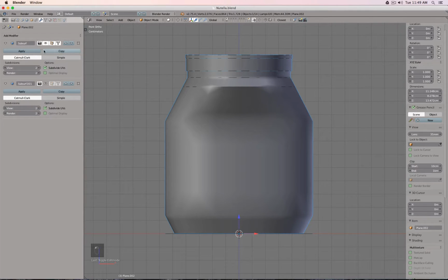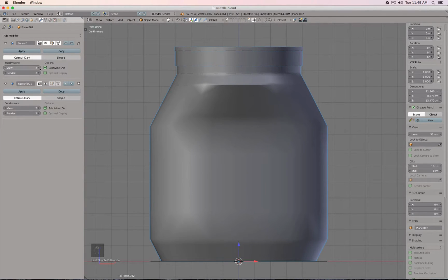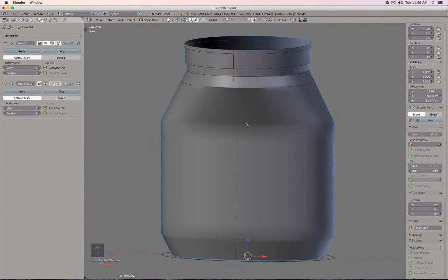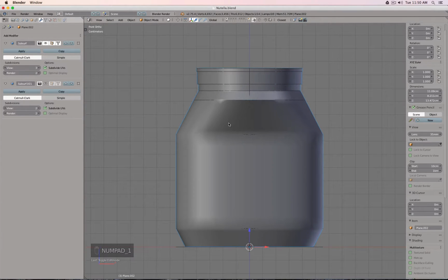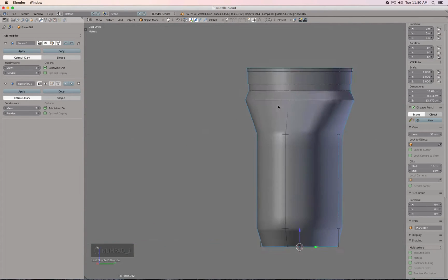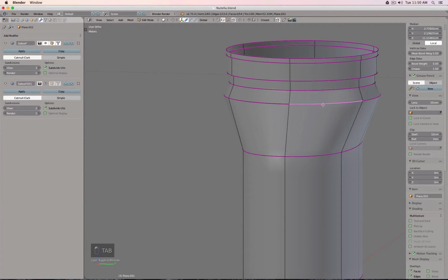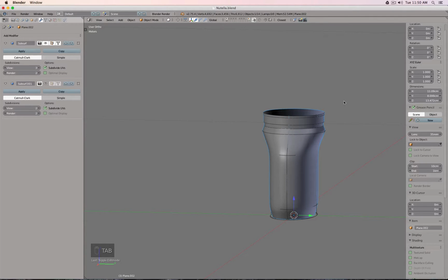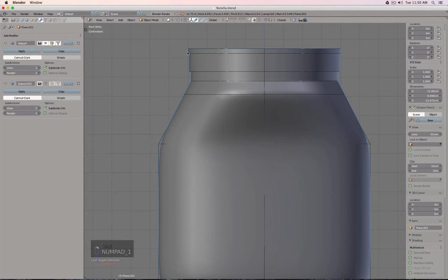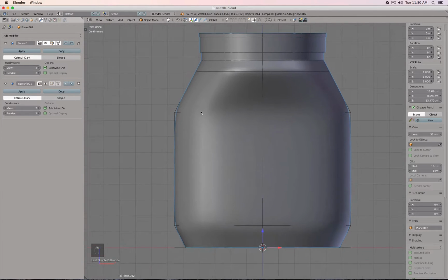And maybe I don't really want this double subdivision trick. Maybe because you can see actually also here it rounds those edges, but maybe I just want this model to be already a little bit more roundish. So for example, here now I simply apply a softer value. So now I have a nice mix between sharp edges and then here this rounds, but maybe this rounds a little bit too much.